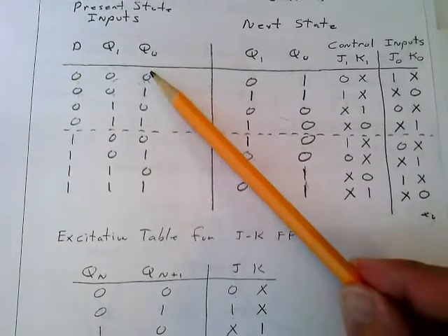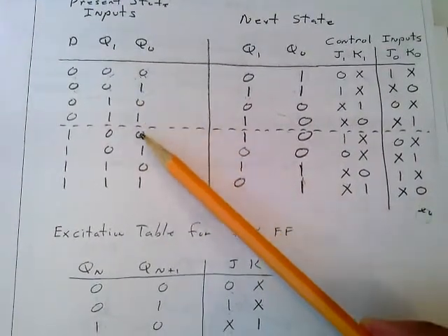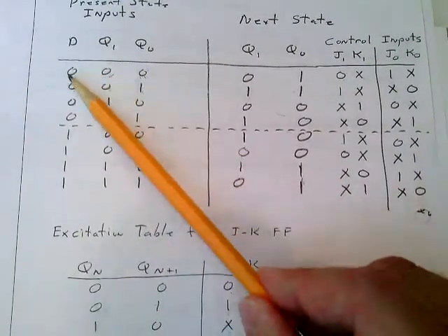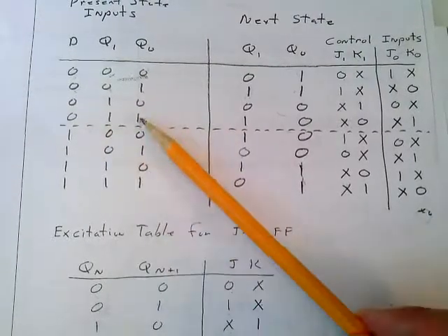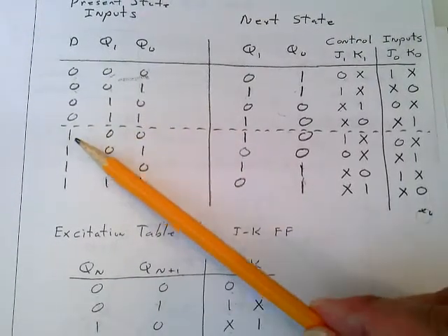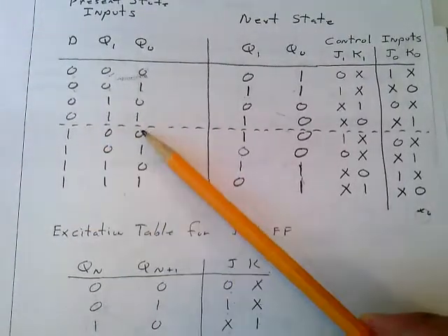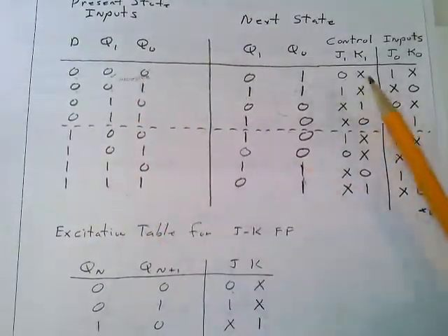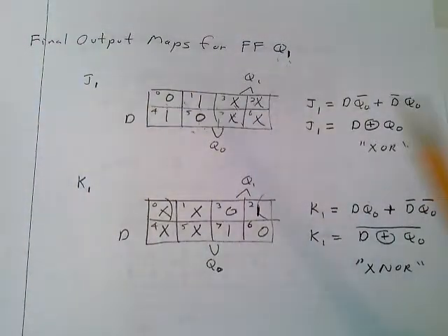With this being state 0, 1, 2, 3, 0, 1, 2, 3. Notice though that I'm looking at state 0, 1, 2, 3, but here, because direction input is 1, it's state 4, 5, 6, and 7. That's all the possibilities here. And when I have the don't cares, I fill in as I go through here.